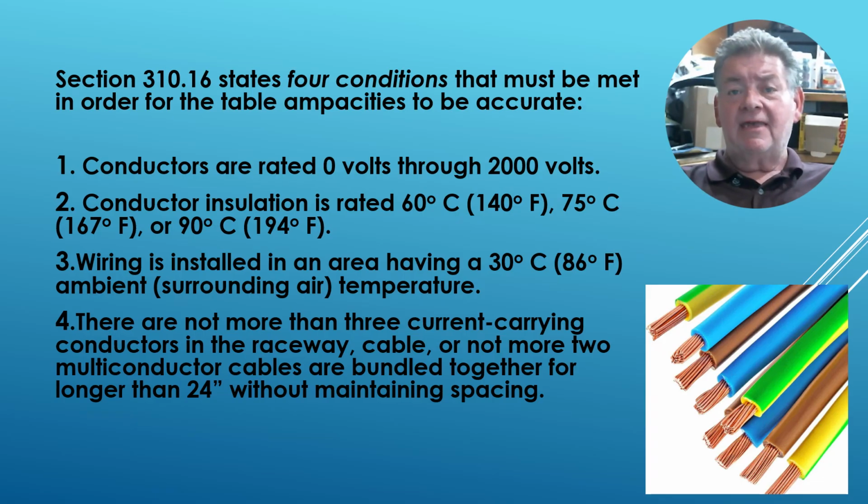Now, I understand that the end result might be that the installation does not look as neat as it would have if you had them all bundled tightly together. But your job has to be code compliant. And in order to be code compliant, you have to maintain some spacing between those cables to allow that heat in the inner cables to be able to dissipate.